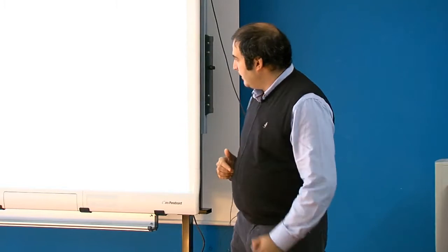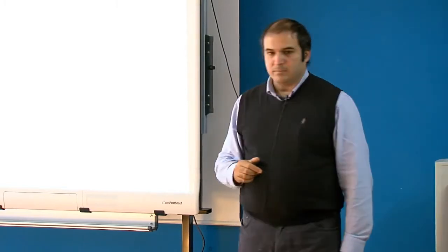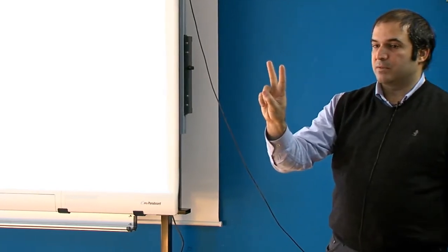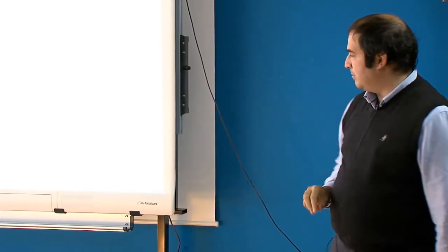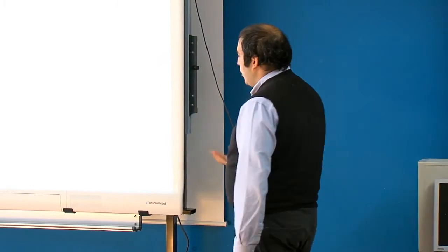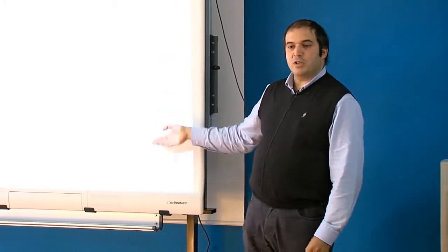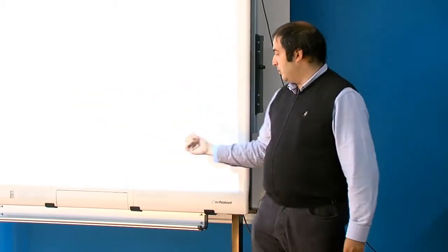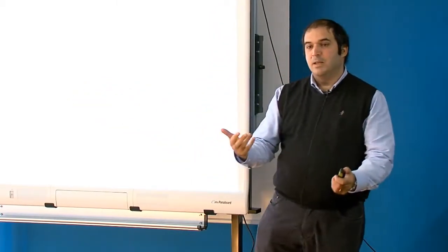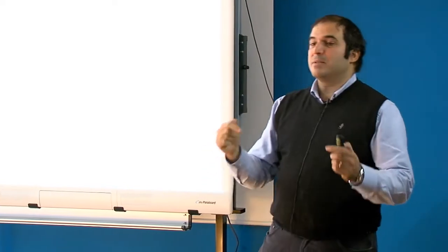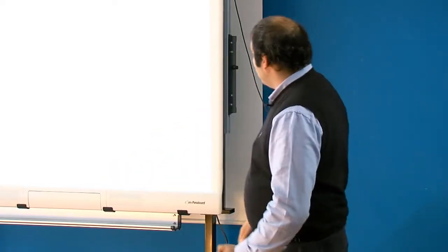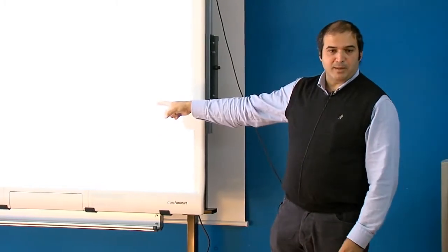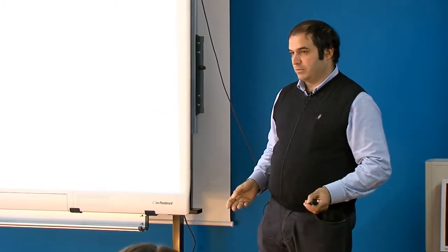Now, I combine these two signals. So I have what is called a two-tone signal. Two sine waves. Okay? I put two sine waves at the input. And my question is, what is the output? Is it the combination of the two? Well, if it was a linear system, it would be the combination of the two. But as I said, a nonlinear system does not obey superposition, so the output of a two-tone signal is much more complex than the combination of the two.